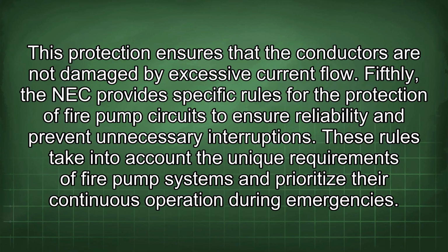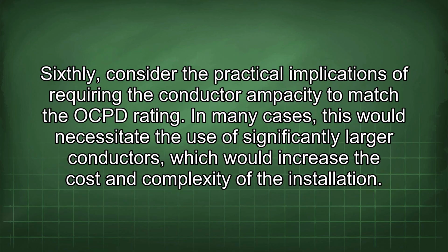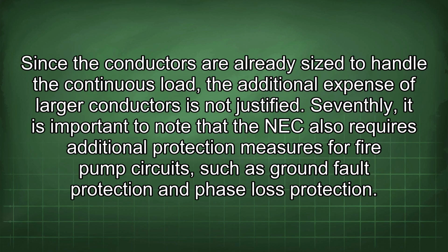Fifthly, the NEC provides specific rules for the protection of fire pump circuits to ensure reliability and prevent unnecessary interruptions. These rules take into account the unique requirements of fire pump systems and prioritize their continuous operation during emergencies. Sixthly, consider the practical implications of requiring the conductor ampacity to match the OCPD rating. In many cases, this would necessitate the use of significantly larger conductors, which would increase the cost and complexity of the installation. Since the conductors are already sized to handle the continuous load, the additional expense of larger conductors is not justified.